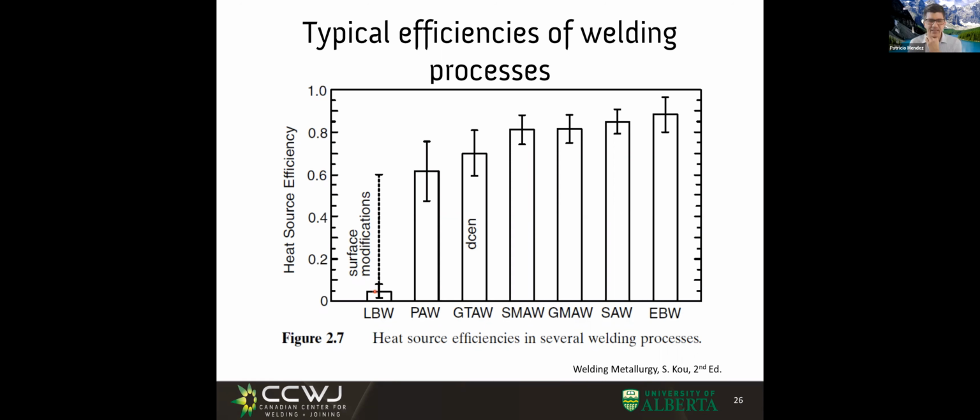Reflection, exactly. So not only is this a problem of waste of energy, of needing a huge laser even for making small welds. Where does that reflection go? Because let me tell you something. The light of the arc can damage you, but you can take 1 second of arc exposure without dying, with certainty. But if a reflection from the laser catches you, yeah, it might catch you in half. So the reflections of lasers are something we need to care very much about.